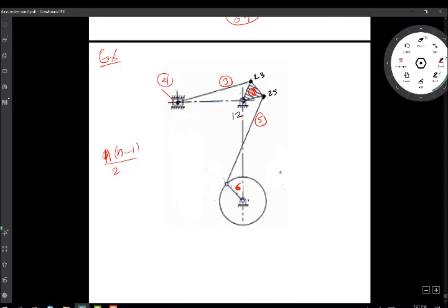The pivot will be point 3, 4. How about 1, 4? 1, 4, of course, is perpendicular to the sliding, and at infinity, this is point 1, 4. So we know 1, 4 is going in perpendicular to that. At the other end, this point here is point number 5, 6, and this point is point number 1, 6.